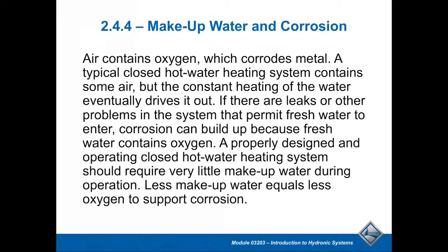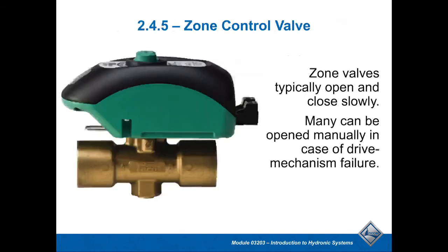On a system where you're running all non-ferrous metal components, it's, I would say, less of a concern, but it certainly is a concern with any component. For example, even if you have all non-ferrous components, if you happen to have a boiler or a circulating pump in the system that's cast iron, you now have ferrous metal components. So that will tend to create a problem for you. The whole goal in any closed hot water system is that we want as little makeup water as possible. We want to try to minimize that. So that's really the goal of that.